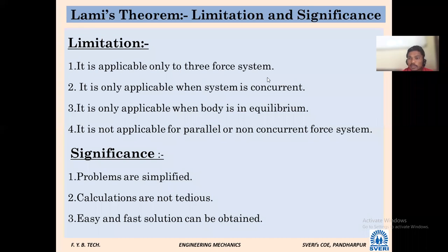It is applicable to three forces. They should be concurrent, and all these three forces should bring the body into equilibrium. It is not applicable to parallel or non-concurrent forces. So if there are three forces which are concurrent and which bring the body into equilibrium, then only we can apply Lami's theorem. We have to remember.